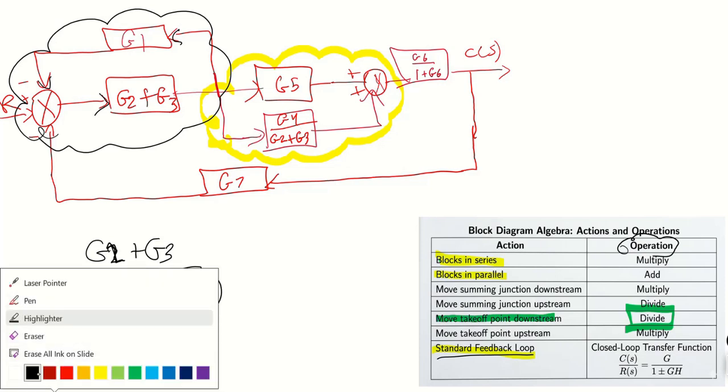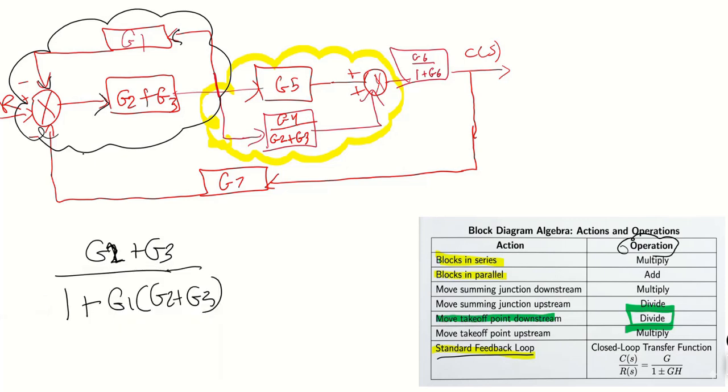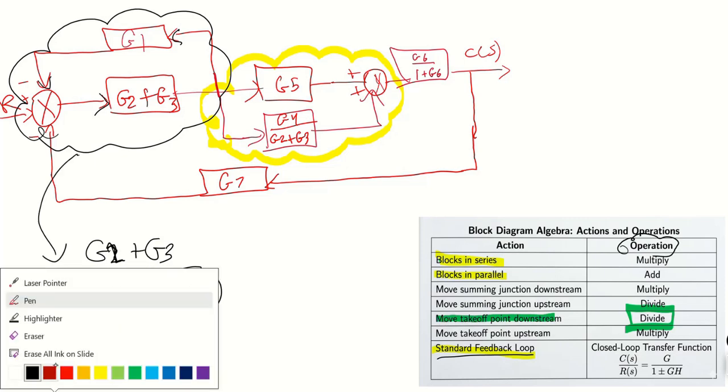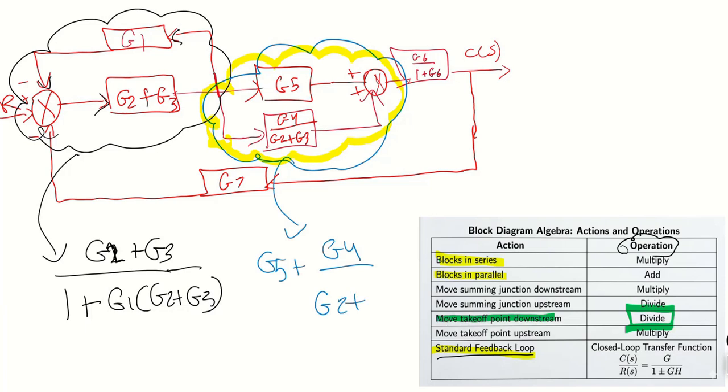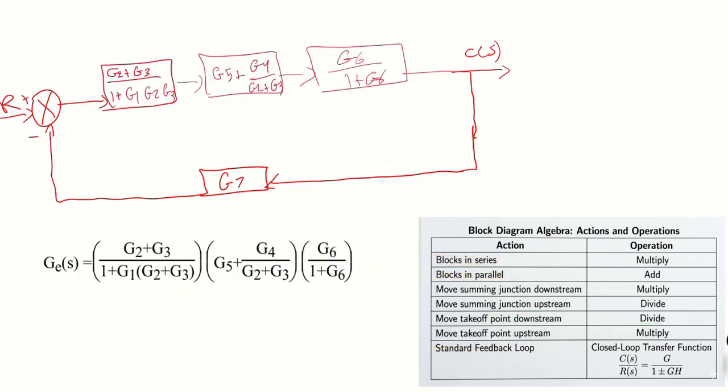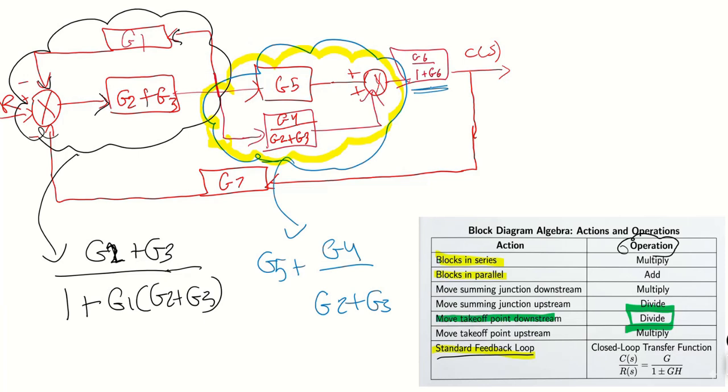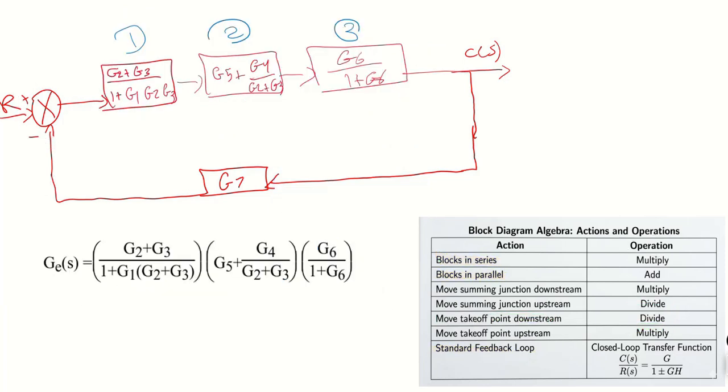So what kind of operation can I do here? We can simply add them because they are connected in parallel. Therefore, we end up with the following blocks simplified in this way. We do have the block from the transfer function, then the second one from the parallel connection, and the third one, which, let's not forget about it, is from our first feedback loop.